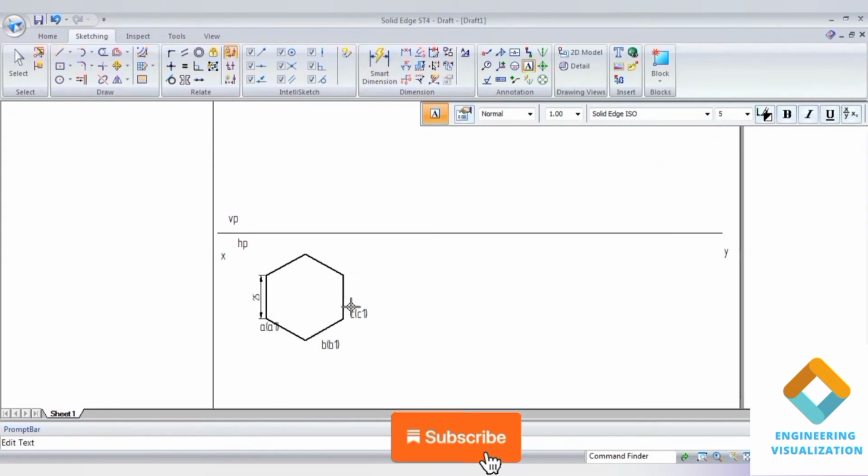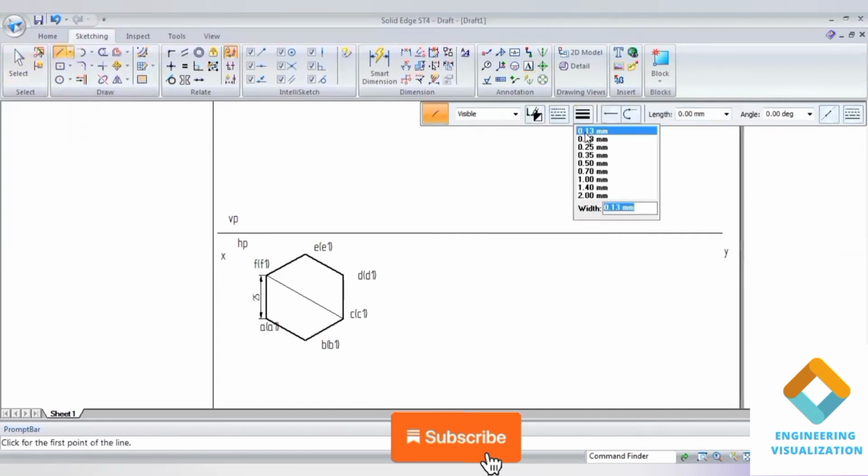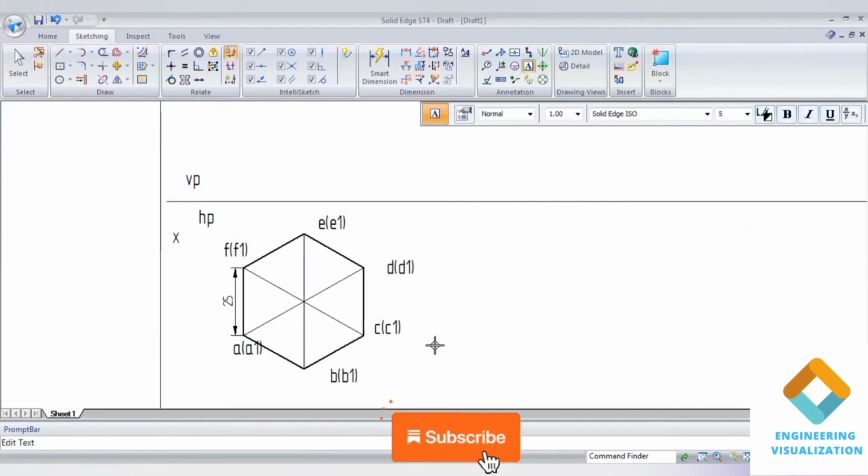So here we need to find out the center of the hexagonal prism. So for that at least one or two lines need to be drawn, because since it is a prism, to find out the center of the axis no need to draw all the lines. And here inside of this hexagon we should be drawing the thin lines. No need to draw the thick line, thin line should be drawn here. One or two lines is enough. Okay, you can see in this problem I have drawn the three thin lines. Okay, since it is a prism we should be drawing only the thin lines, not the thick lines, and mention O1